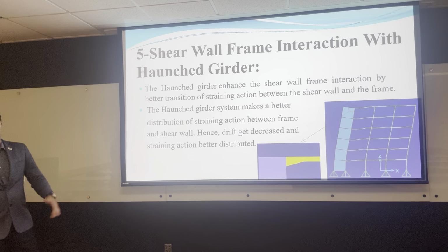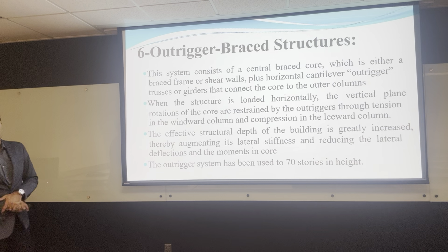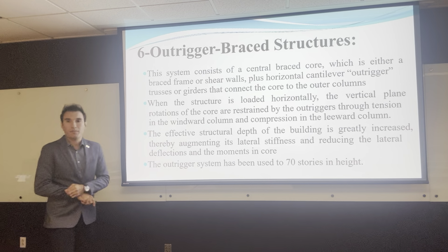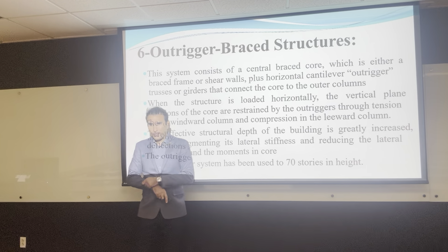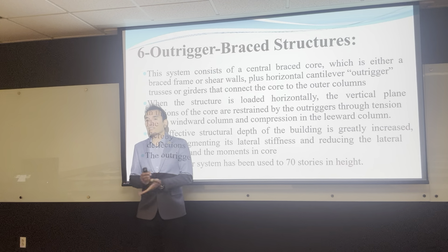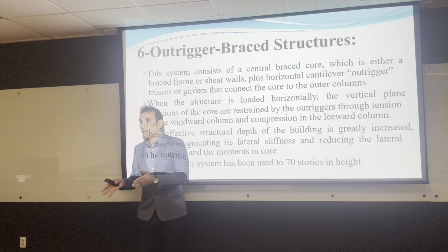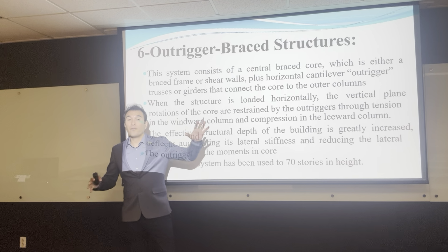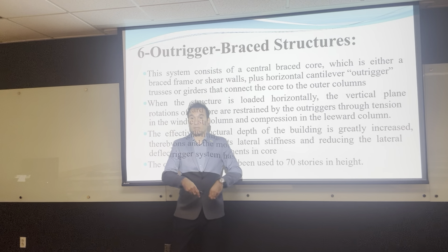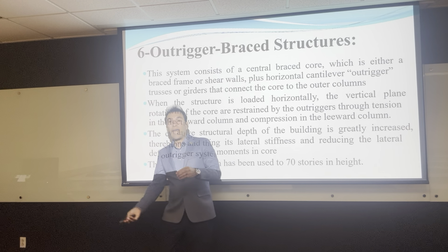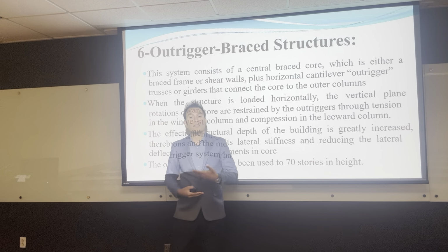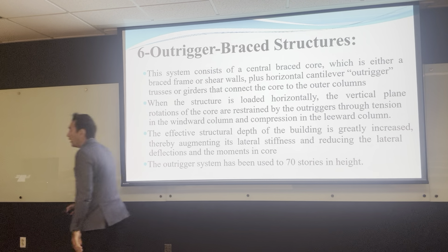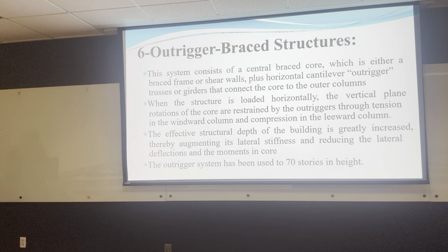Let's get into more interesting systems. There is a system called the Outrigger system. Have you guys heard about this system? The Outrigger system is something innovative. It's not a separate system. Actually, you have to have shear walls and you have to have another special system inside your building. So it's something that you can add to your system to enhance the lateral load resistance of your building. So I'm going to draw it on the board.